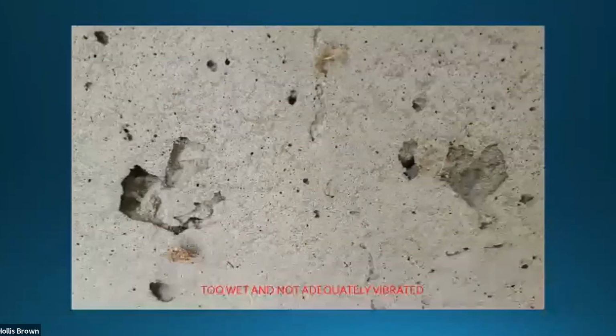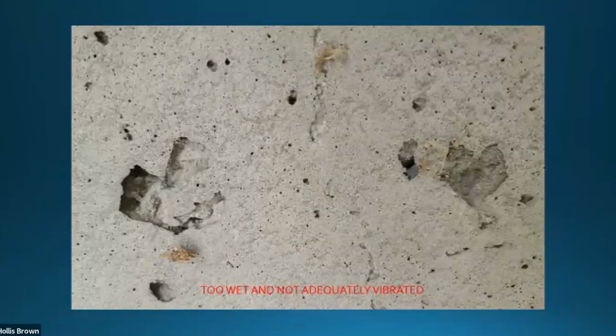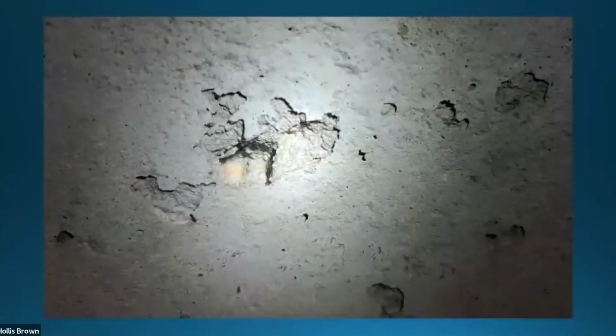That's another shrinkage crack. This is clearly concrete that was too wet and not adequately vibrated. That one, the jury's out. There's not a whole lot of porosity to it, but there is some.